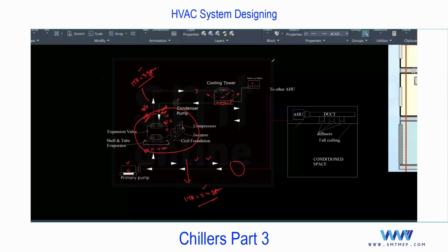One more point, this is also an important point. For example, compare this chiller, for a big project, if you use a DX system, you need to supply the refrigerant for the entire FCU and AHU, and compressing that much refrigerant requires a very high capacity compressor.